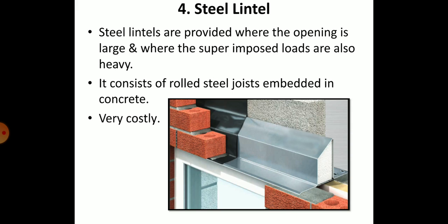The next is the steel lintel. So what is the steel lintel? Steel lintels are provided where the opening is large and where the superimposed load is heavy. The steel lintel consists of a rolled steel joist embedded in concrete, and these lintels, being very costly, are restricted in use to special cases.